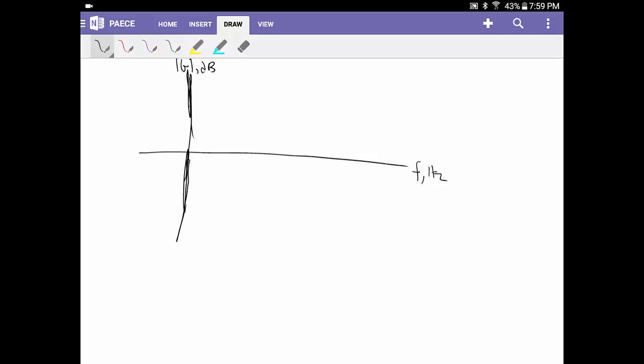A bandpass filter filters out all frequencies except for a specific range. And you noticed this in the last lab when you measured the cutoff frequencies at the low end and the high end of your BJT amplifier. So our bandpass filter should look something like this. There's going to be a point which is our FCL, our low frequency cutoff point, where it's going to go off into negative infinity up until this point. Then it's going to flatten out and be nice and flat and linear like we wanted. Then after a certain point, we're going to have our FCH, our high frequency cutoff. And then it's going to start rolling off again towards negative infinity, or 0 gain, fully attenuated.